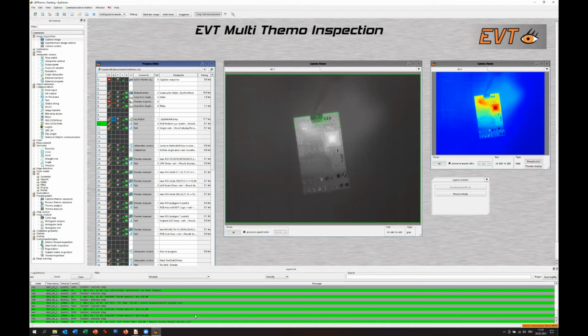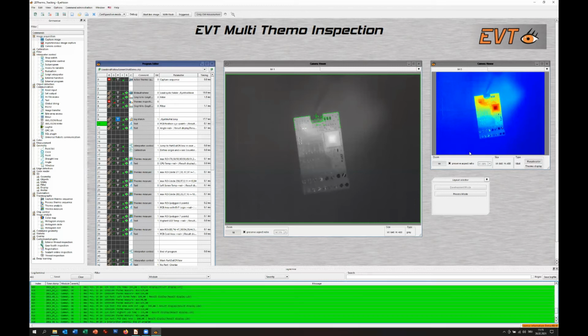But on smaller systems, you should consider whether to switch the text output on or off, and you have the same options as the graphic overlay: either always, only in OK, only in not OK, or never, which also reduces the output here, because if you only print output when an error occurs, then you see the error. Of course, these log files are written from the very beginning when the iVision software starts.